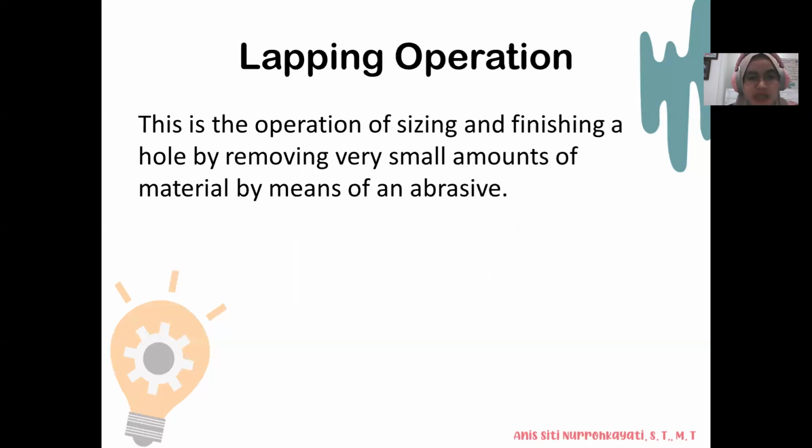Next is lapping operation. This is the operation of sizing and finishing a hole by removing very small amounts of material by means of an abrasive. So the abrasive material is kept in contact with the side of a hole that is to be lapped by the use of a lapping tool.